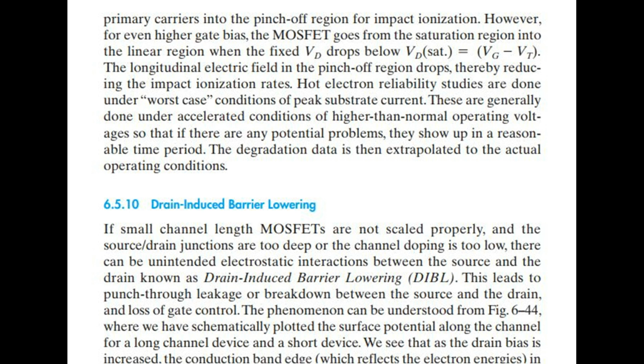Drain-induced barrier lowering. If small channel length MOSFETs are not scaled properly, and the source/drain junctions are too deep or the channel doping is too low, there can be unintended electrostatic interactions between the source and the drain known as drain-induced barrier lowering, DIBL.